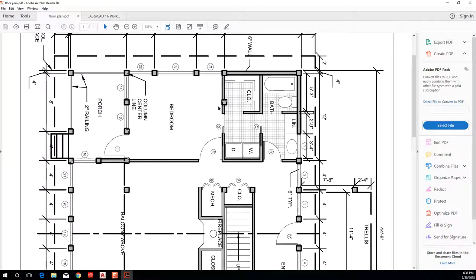The other thing I want to talk about with regard to reading a set of plans is how we're viewing these drawings. What I mean by that is when I look at a floor plan, I am not viewing it from 7 feet above the floor. The definition of a floor plan is essentially taking a building, an enclosed architectural space, and cutting it horizontally at a 3 to 4 foot height. And anything that you cut, you're going to see in that floor plan, okay?